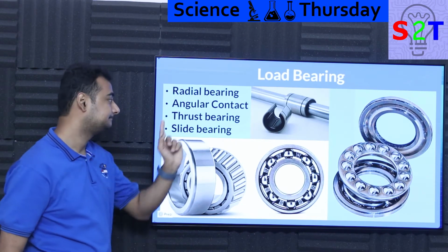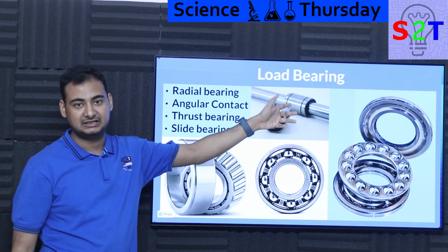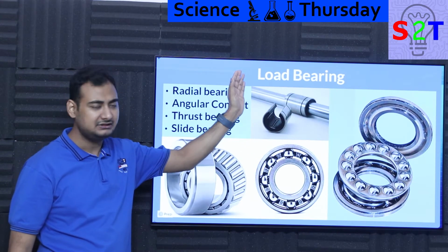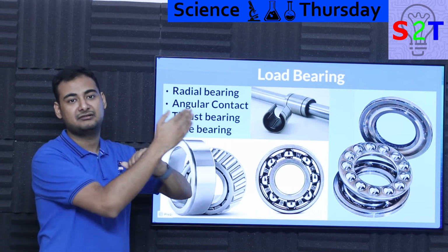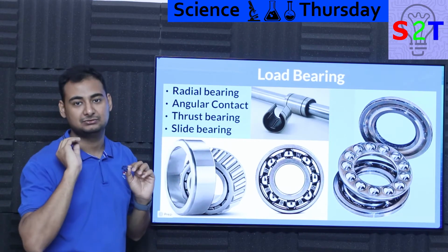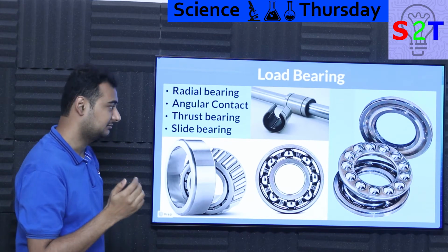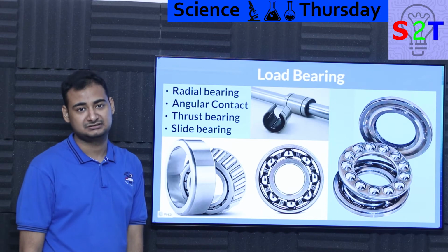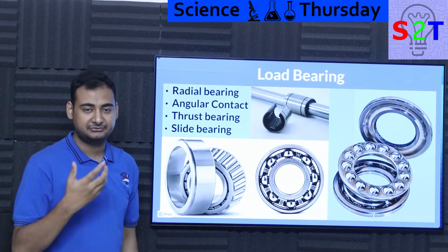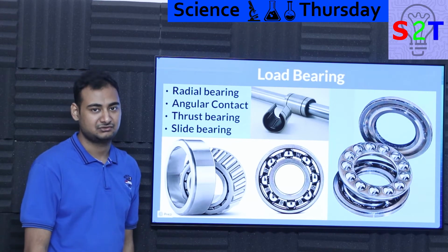You never want sliding. So a linear bearing, wherever you see a Prusa printer or things of that nature, all this thing is trying to do is have the balls touching each other one after another. You never want it to slide on top of each other, because if it slides, no matter how much lubrication you put in there, over time it's going to heat up, and that heat will push out the oil, and then it will end up destroying each other.